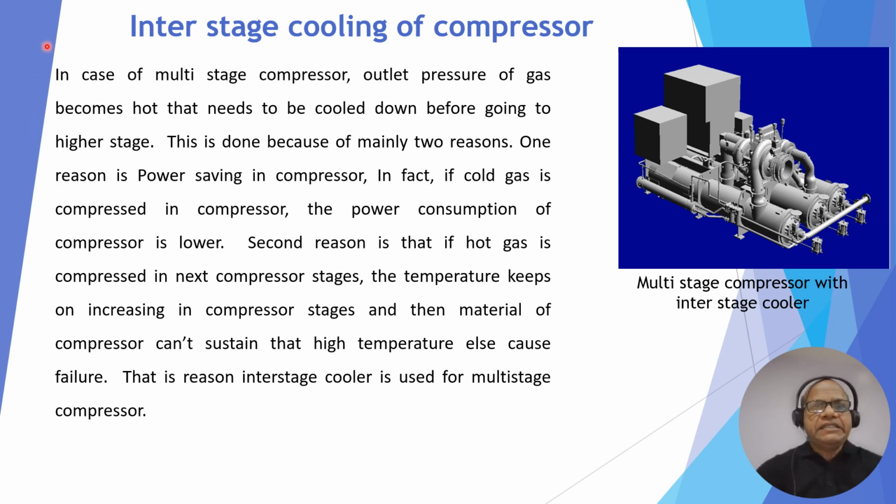Now, why is interstage cooling of a compressor required? This is another aspect or requirement. Look at this multi-stage compressor. In between is an interstage cooler. So the high pressure, high temperature gas of, let's say, the first stage comes out and goes to the next stage, and before that it has to be cooled down in a heat exchanger.